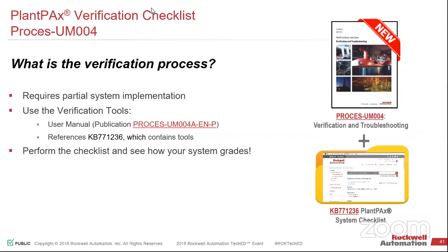It goes through and asks you a whole bunch of questions. You just fill out this Excel spreadsheet with, you know, how many servers do I have? What's the loading on them? CPU loading, memory size. How many pages do I have on my HMI? How many tags am I pulling? How many am I pulling continuously? And it goes through and analyzes all those and tells you whether you're good or not. It'll give you that green, yellow, red analysis of each of those things.